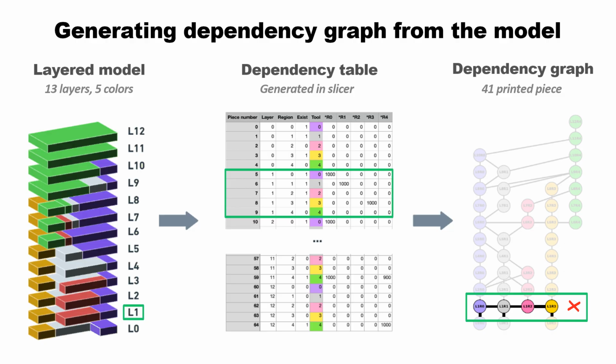Since the pink region L1R2 is new and there is no connection with regions below, additional connections are made with all other nodes around it to ensure the structural integrity of subsequent layers. Thus, we assume that in order to fabricate this pink region, all surrounding regions must be fabricated first, which implies a dependency on fabricating those regions.